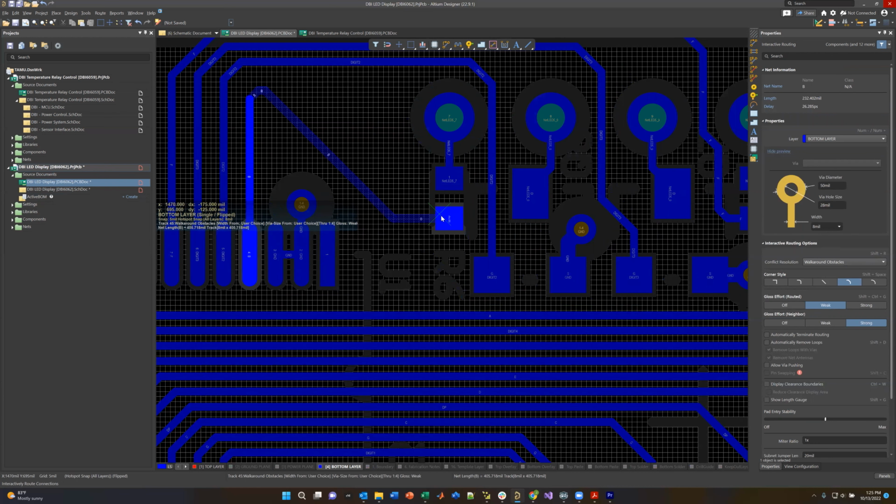So this here actually connects, this is again single layer mode, this terminal block to the relay and the MOV. Same thing happening here. These traces are both on the top and bottom side to carry the current. I used the trace width calculator that I've mentioned before in class to calculate the appropriate size of the trace to carry the 10 amps through the relay.